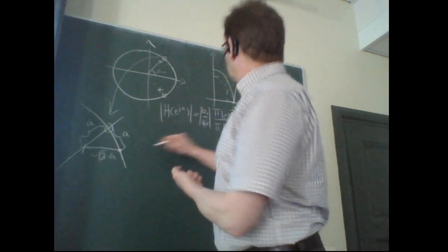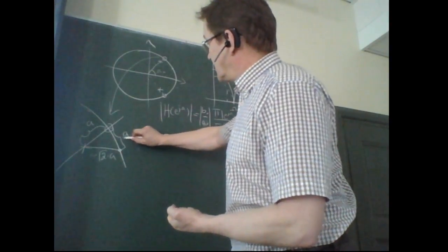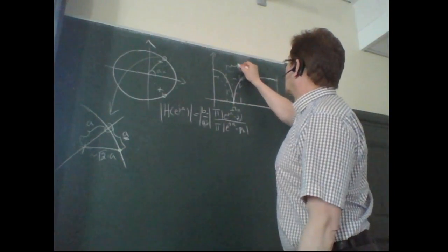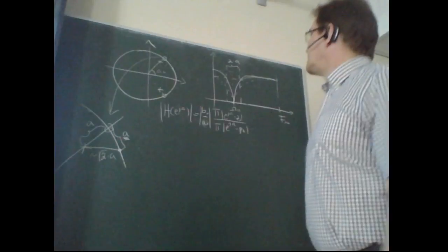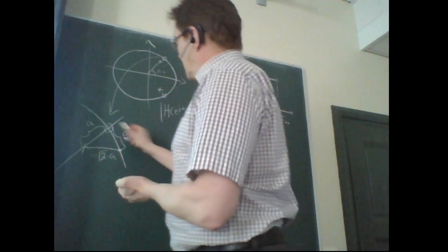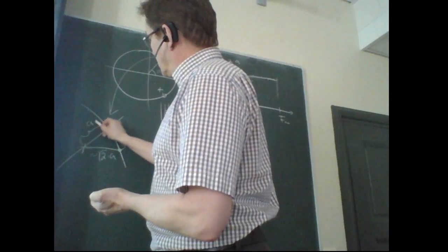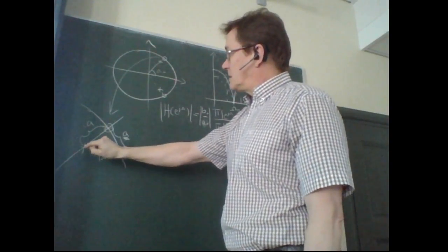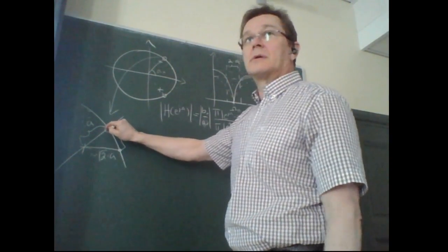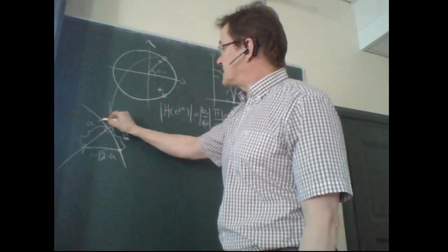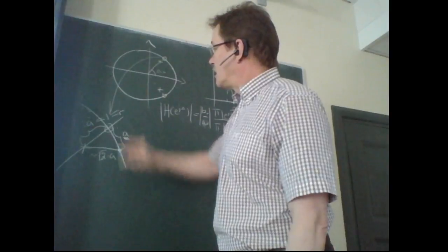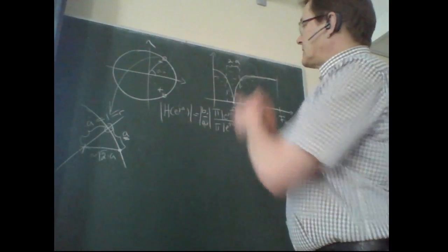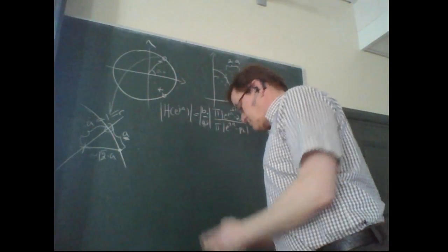So basically, if you want to have a certain minus 3 dB half width, so this is 2 times a, then you just plug it in this equation as the distance from the pole to the unit circle, which is at the same time basically 1 minus the radius. Okay, so that's the first part, I think.